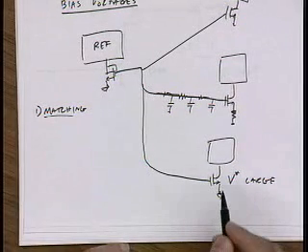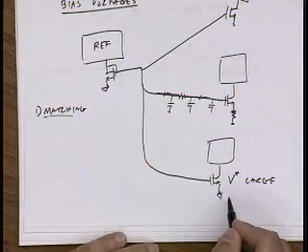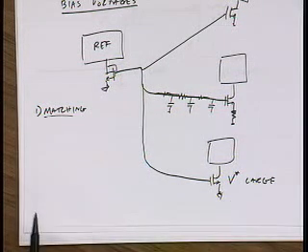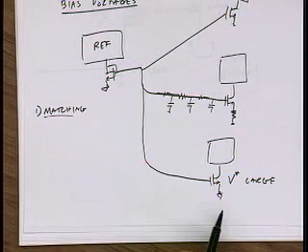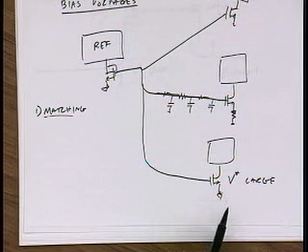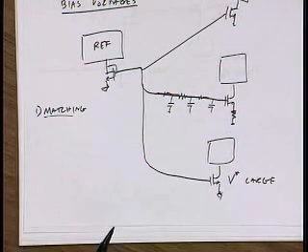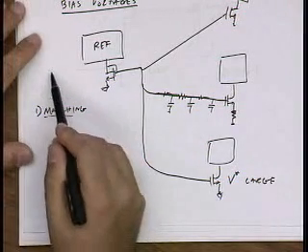So I think one of the most dangerous symbols electrical engineers invented was the ground symbol, because it's this nebulous concept. Oh yeah, it's ground. But in reality, when you lay out a chip, you realize, wait a minute, how does ground get to this point? Certainly I'm not going to rely on the substrate to be my ground, right? The substrate is too resistive and too noisy. So usually there's some kind of ground bus in your chip.